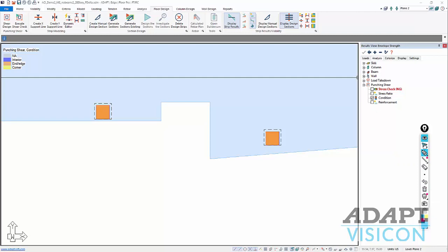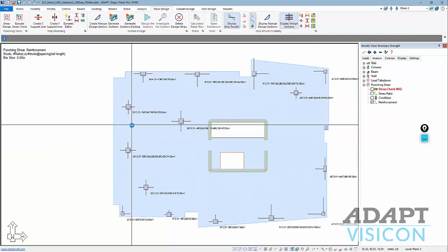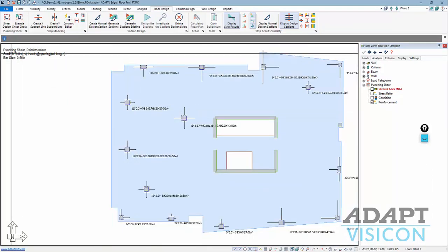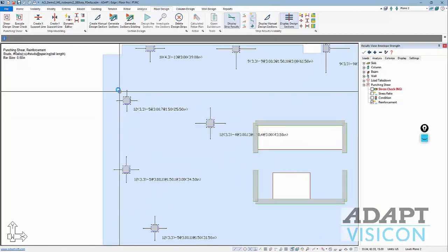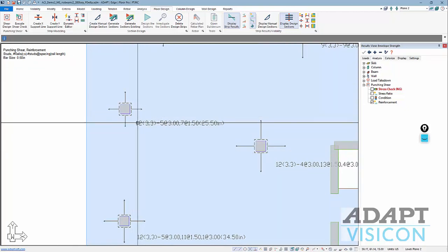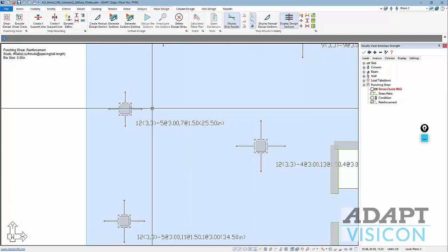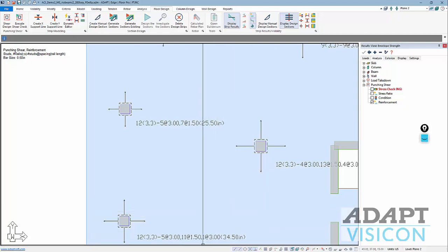Finally, if we go over here to reinforcement, this gives us an indication of the reinforcement. And what this means, we have a legend here, so I recommend the user follow that legend. This kind of tells how this is spelled out. So if we take a look at this column right here, this tells us that we have 12 rails total. There are 3 rails per side necessary to meet the 2 times d distance between rails in a peripheral row of reinforcement.